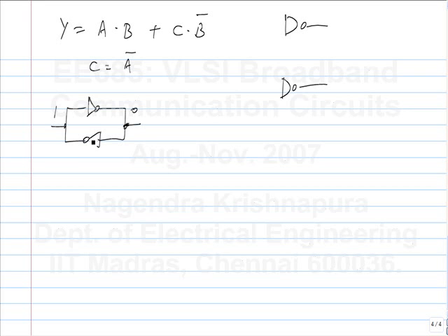Now, it's not enough to just have this. We also need a way to write the values into it. So that's why we use a gate. We know that the NAND gate is an inverter if one of the inputs is a 1. By appropriately changing these two, we can change the state of this. Whichever side we want to write a 1, we pull the other to 0, and that will get a 1. And when both of these are high, the state will be retained.